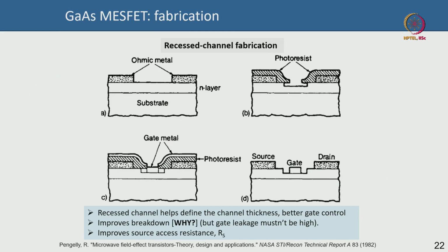Okay. Now, that is fine, but in most MESFETs people use a recessed gate, as I talked about in the first slide of this presentation, and recessed channel is a necessity because it helps you improve the breakdown, it also helps you have better control of the channel, therefore you are going to get better transconductance or GM. How do you do channel recess?